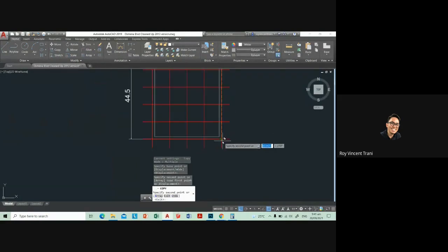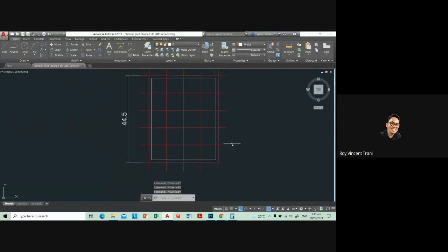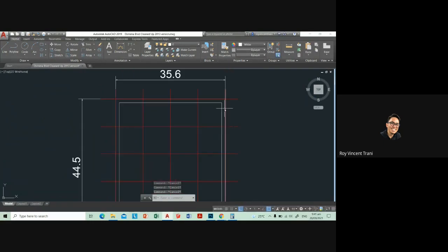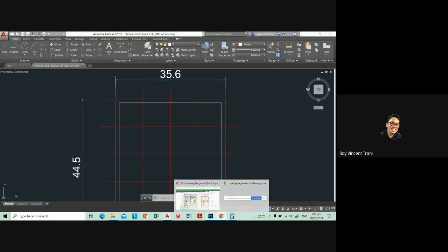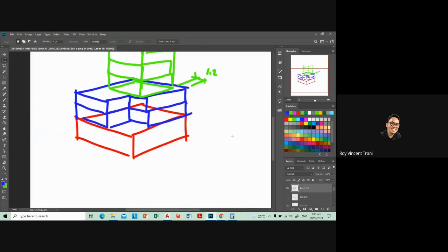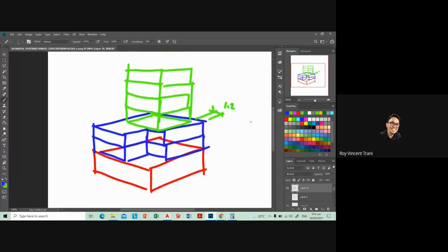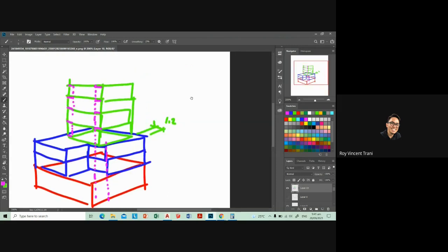It's fitting like that. You'll need to have, kung ano mo set up and you want to use that 1.2, you can do something like, what do you call this? Cantilever na beam. So, for example, you have a column that goes all the way from the basement to the upper floor, something like that. And then this stops here, so second floor lang. And then you'll need cantilever slabs on this end. So your upper floors will probably look like this, like cantilever diha. So that's one option. That's the easiest option.